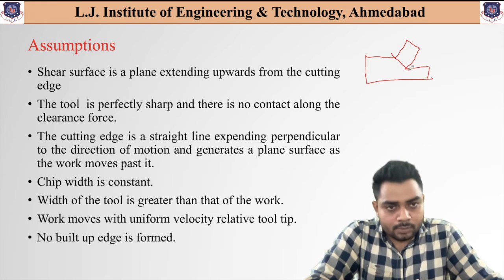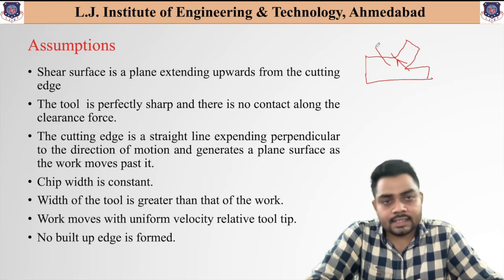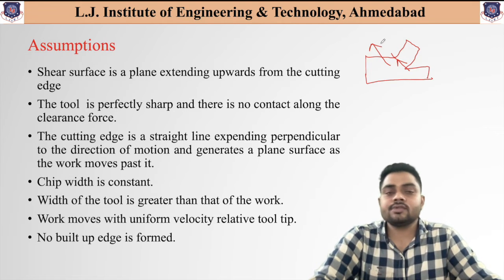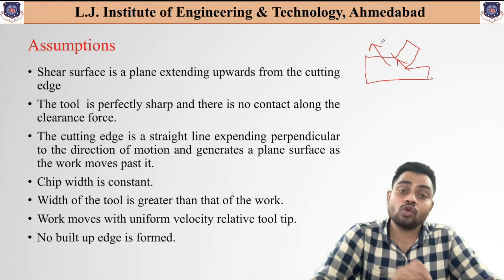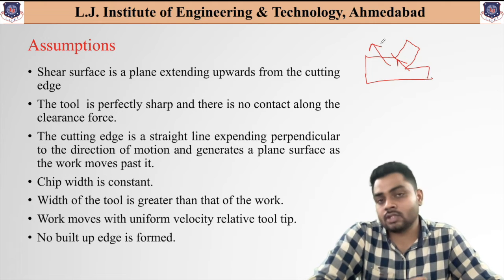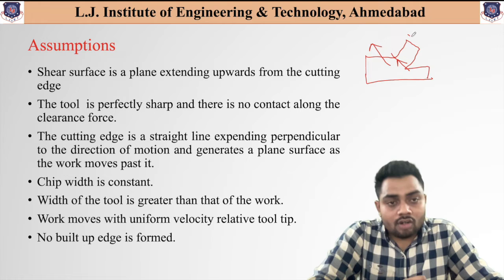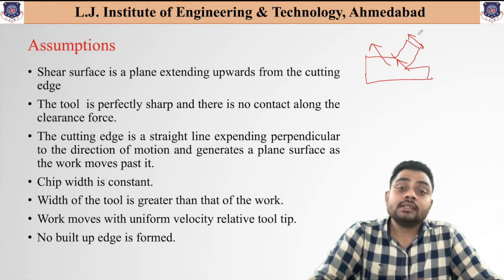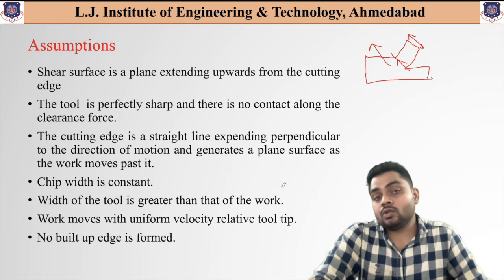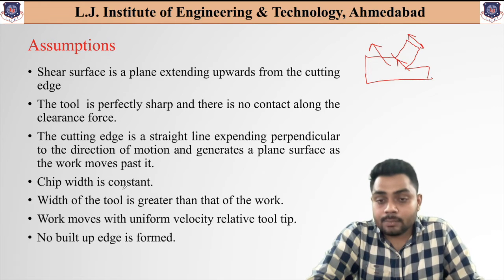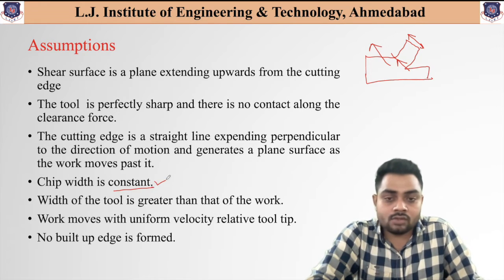And the chip removal takes place in this particular direction, which means the shearing force is acting in the upward direction only. So we are assuming that this shear force always acts in the upward direction only. Then the width of this chip, the actual width, also remains constant after removal. So we are making certain assumptions, which are mentioned over here.